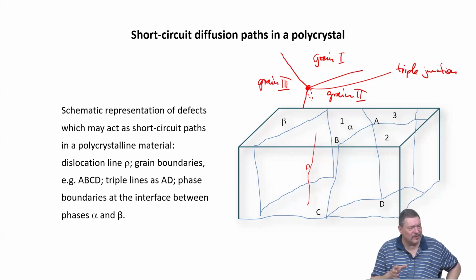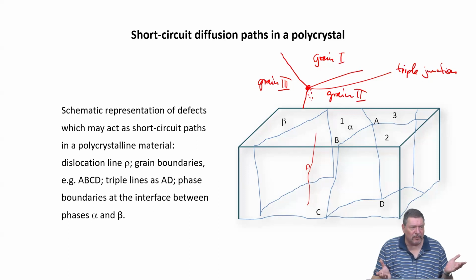And so far it has not been solved, but our results indicate that actually it is what you indicated, that it's not so much different from dislocation pipe diffusion. Maybe a little enhanced, so it's going between grain boundary diffusion and dislocation pipe diffusion, and there you're absolutely correct, it could be different for different systems. And then also the local stress distributions play a big role.